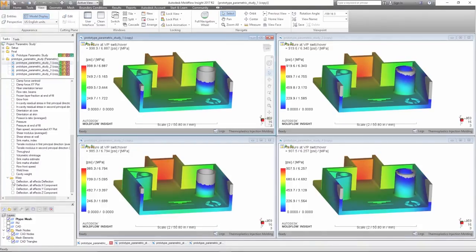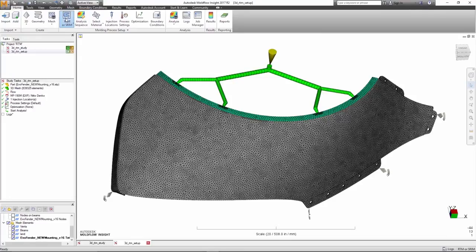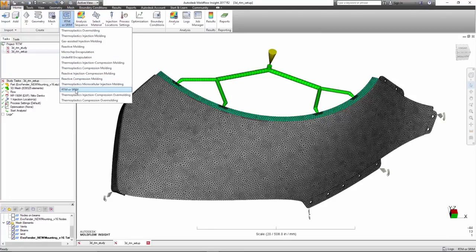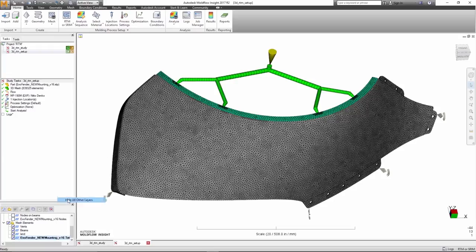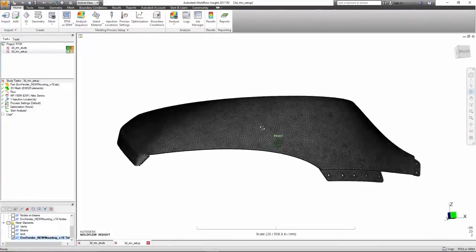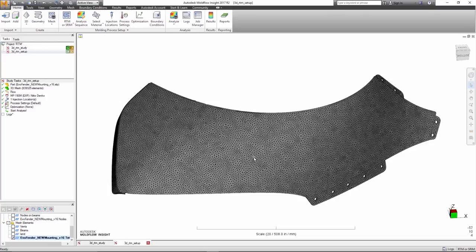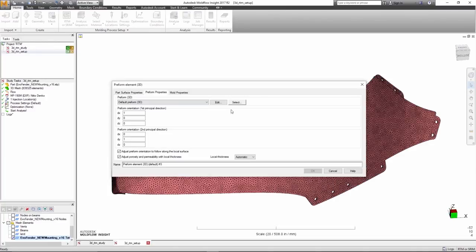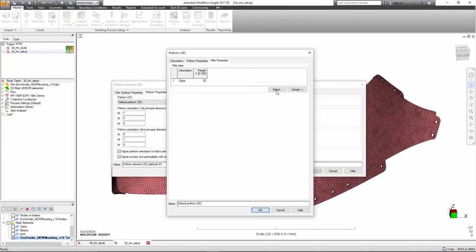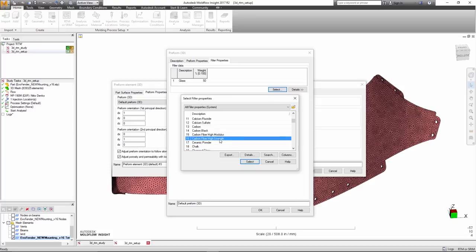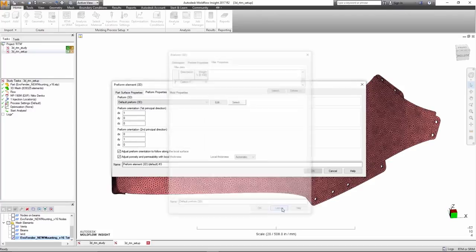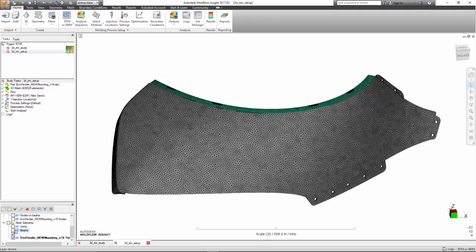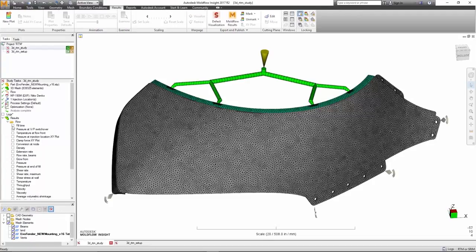In the resin transfer molding and structural reaction injection molding analyses, resin is forced to flow through a cavity in which a reinforcing preform is present. The reinforcing preforms are typically carbon fiber or glass fiber mats that are placed in the mold in dry form, and a thermoset resin is injected. Once the thermoset is hardened, the new product forms a lightweight, hard, and strong composite structure.